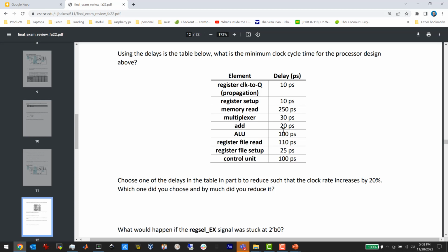So you'll see I have it worked out, but the fetch, execute, and write back are different. They have different combinational paths in each stage. You have to find the longest one, right? And that one is your critical path, and that's going to determine your clock, right? And this one has memory.